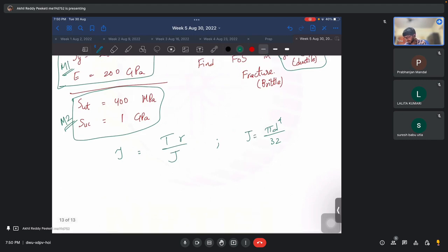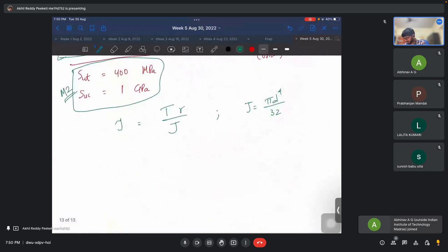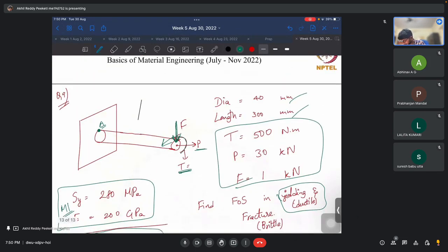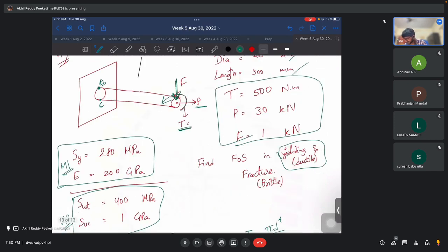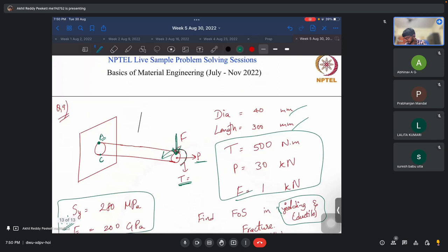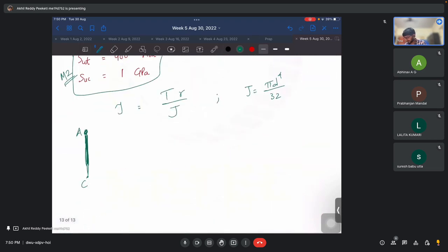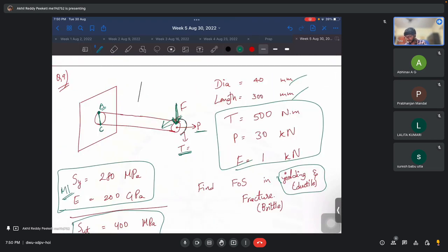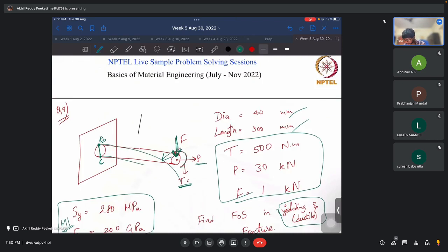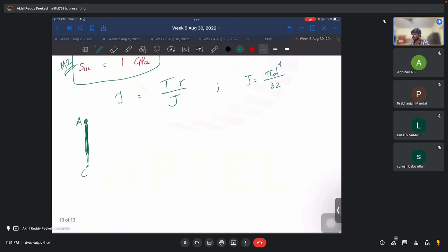Now, what would be the axial stress in this case? If you look at point A, and then see point C, I am looking at the diameter at the vertical central line. Okay. Now we have F, which will cause bending. So the system would bend something like this. How will the bending load be? Here it would be tensile, and as you go down, the lower part of the beam is compressing, so it would be compressive stress.